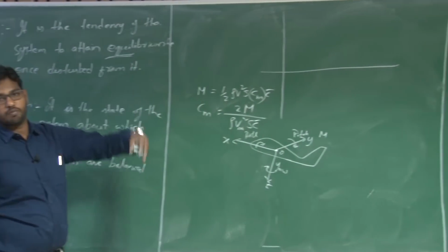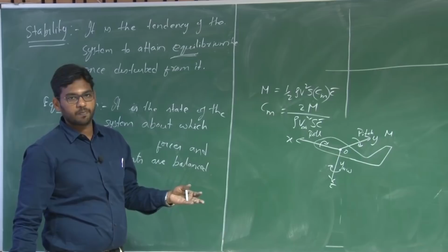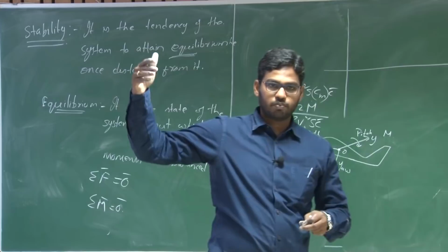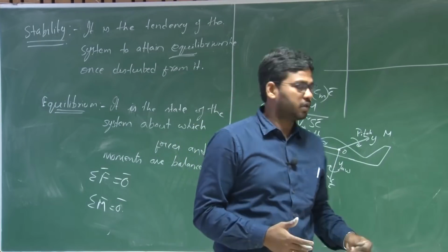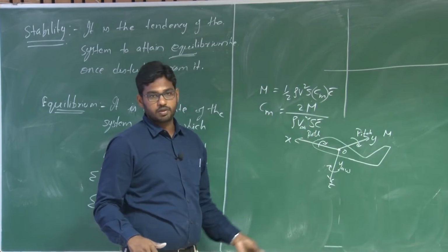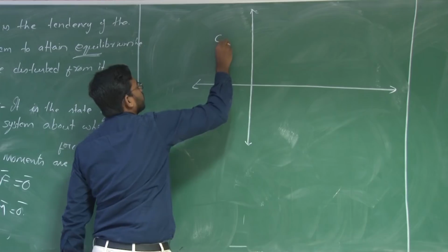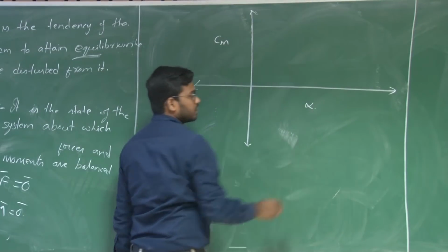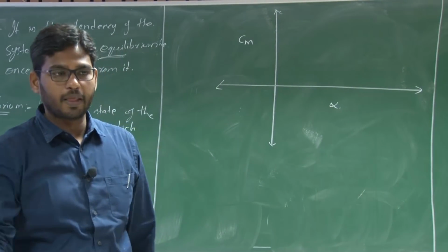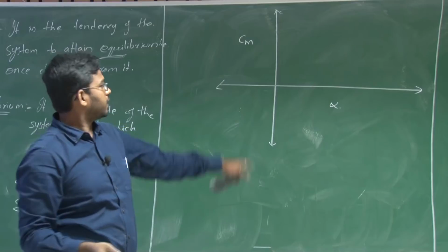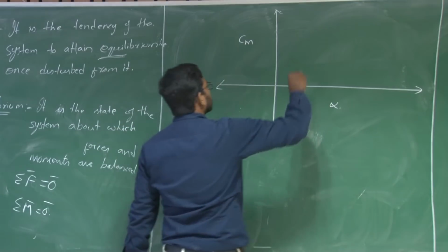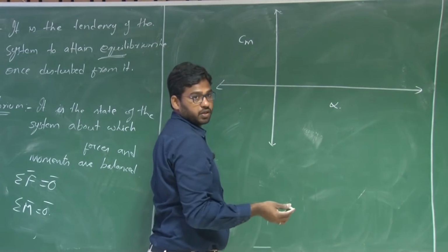Even in the pendulum there is a moment because of the force. So this is the moment because of the aerodynamics. In the pendulum case we have that moment due to gravity. Here, this Cm is a moment that is due to the aerodynamics. So consider the Cm variation with angle of attack. Since it's an aerodynamic moment, these aerodynamic forces and moments depend upon the angle of attack, right. Let us consider this variation of the Cm with angle of attack, say for the entire aircraft or UAV.